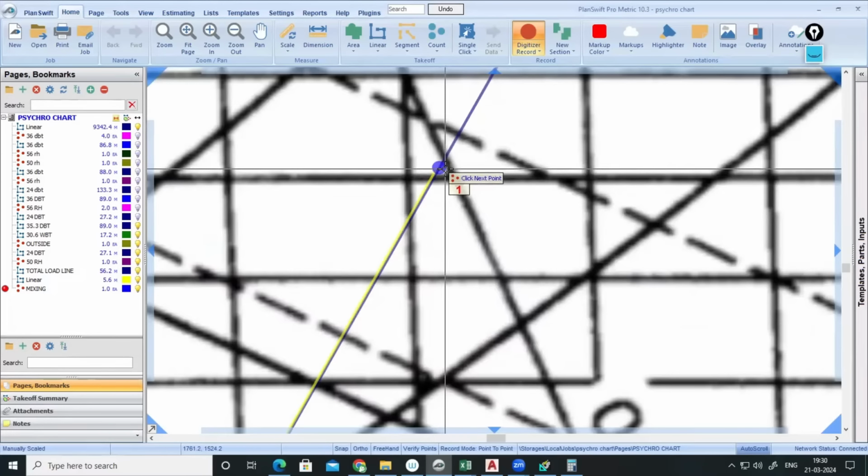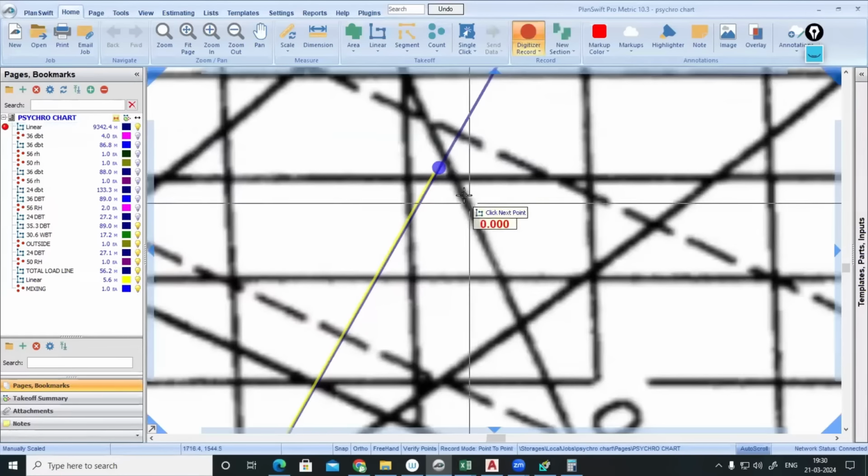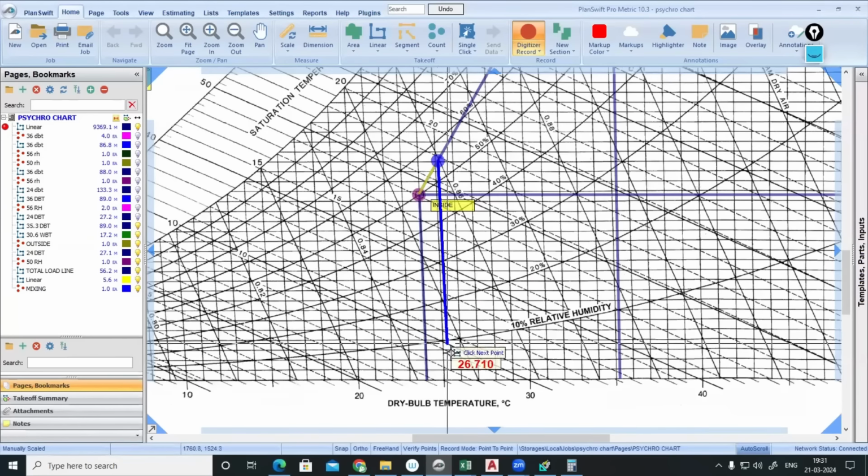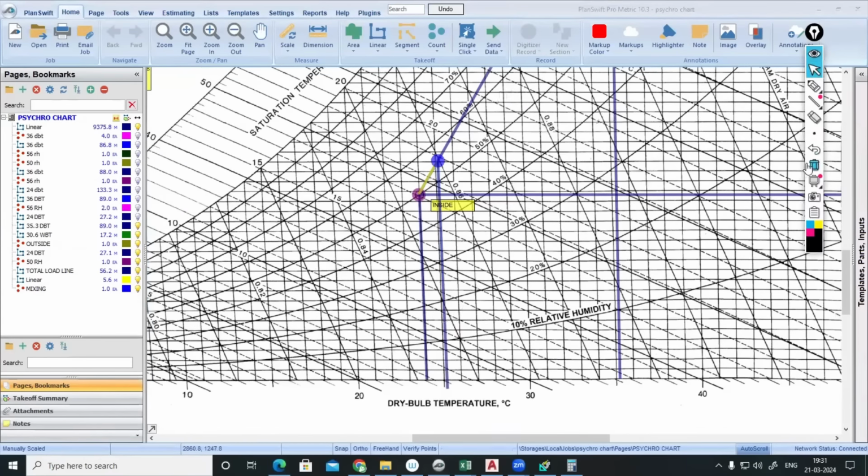Now you can find the temperature. Means when we are mixing the air, at what temperature it will come. From this mixing point, you can make a line down. So what will be the temperature when we are mixing? This will be like 24, 25. When it is coming to the machine, it will be delivering at a temperature of 24 degrees Celsius. After mixing, the temperature will be 24, 25. Let's say 25.2 something will come. This is the mixing point.